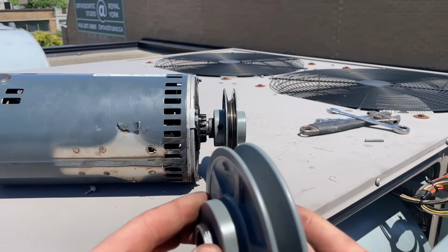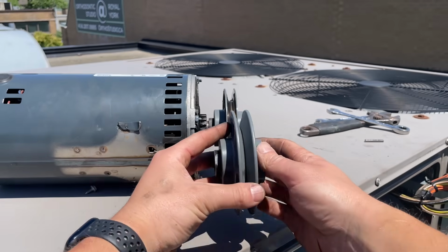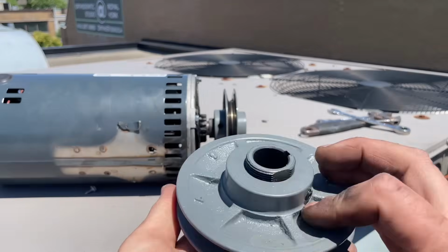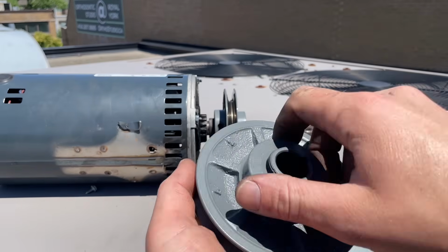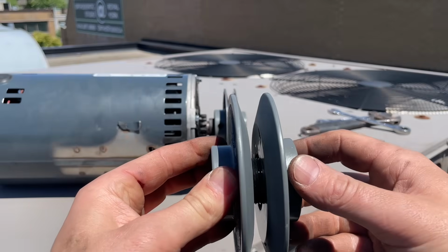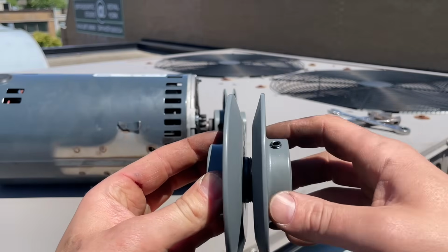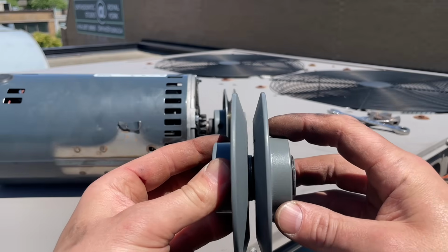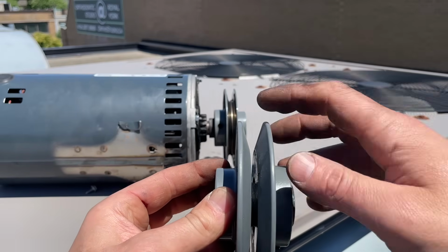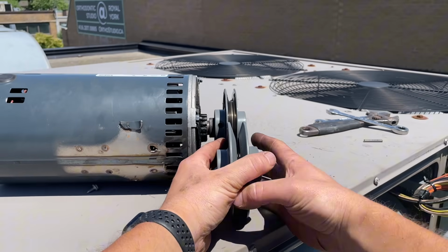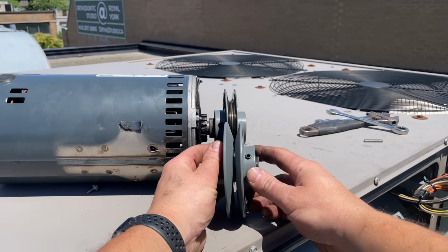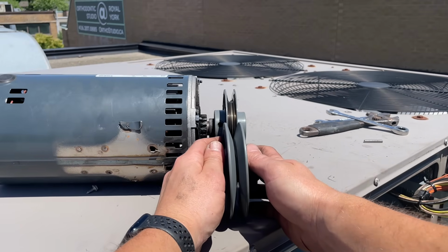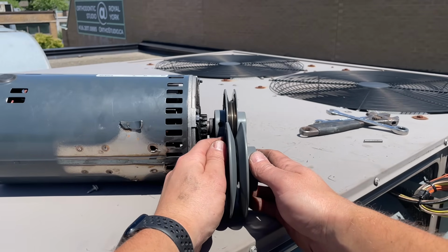Now what we're going to do is match our pulley opening to our old pulley. So that looks pretty good. These are adjustable motor pulleys, so the more that you loosen it, the wider it will get. And when you tighten it up, it will close it off. So that will just depend on how far or deep your belt would sit inside there. So that looks a little bit much. We're gonna try it right around there. That seems to be pretty close.